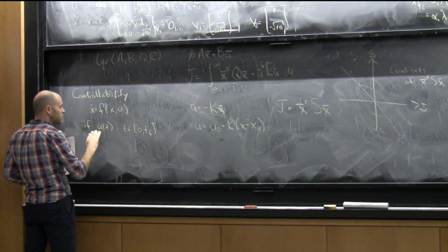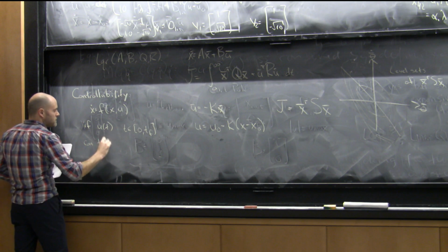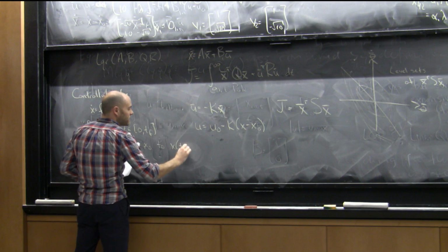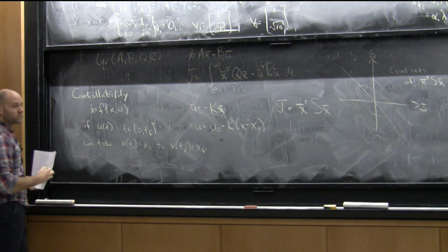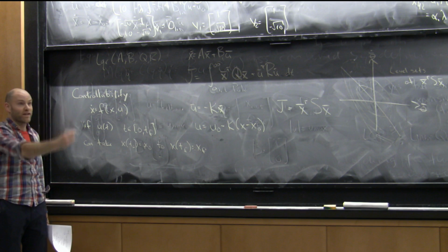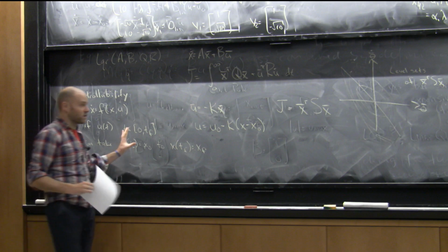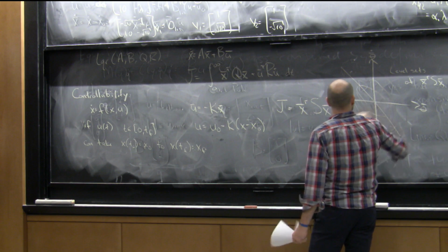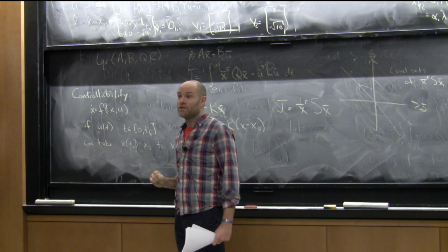The basic controllability theory says if I can come up with some u with finite duration that can go from any state to any other state in that finite time, then it's controllable. So there has to exist the ability to command the system to eventually get to the point. If you have that property for a linear system, even just saying that you can get to the origin, it turns out to be sufficient, then LQR will succeed for any positive Q and R, and we'll find a way to the origin. Yeah? Is this a condition on all x, or just a particular x? It's for all x, to say the system is controllable.